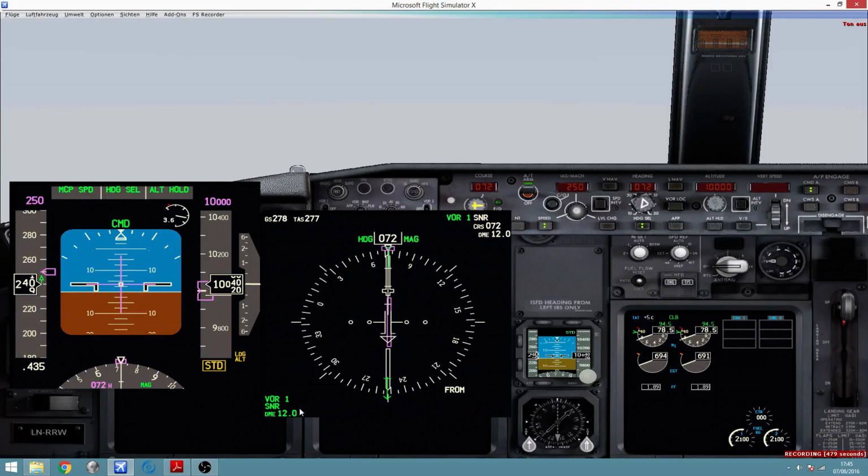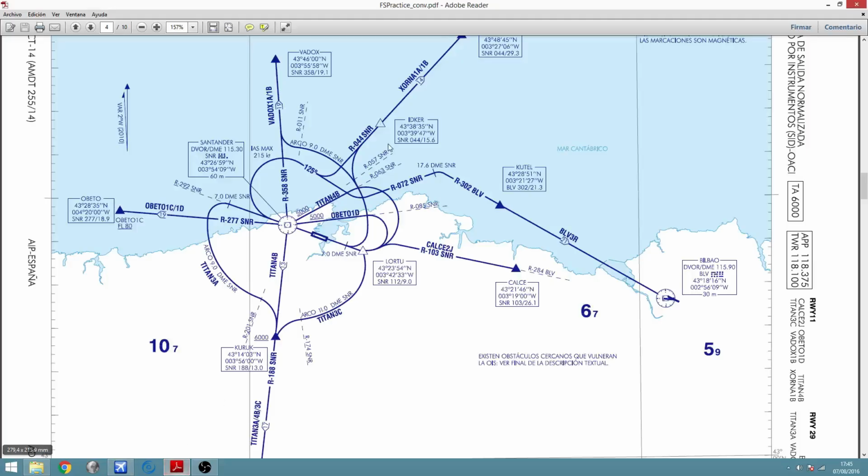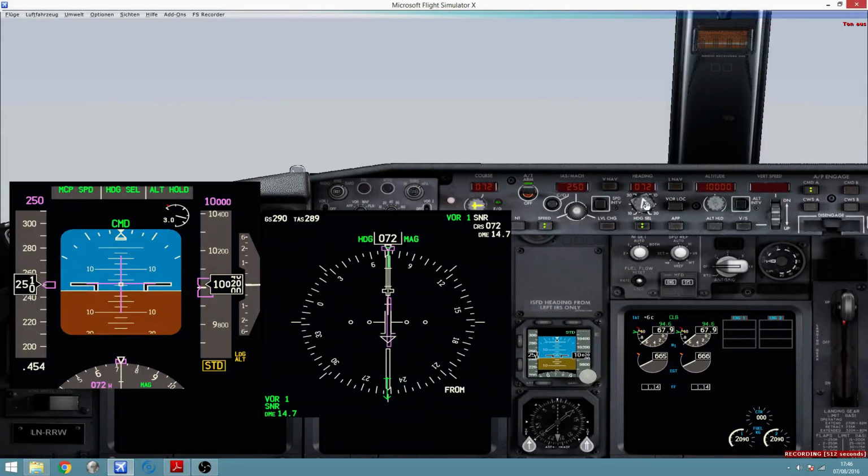Good. I'm only 4 miles from the point that I have selected, that is indicated from this point. And at this point I will continue turning right. On which track? I will look for a track of 302. No, this 302 degrees is outbound from Bilbao. The opposite one should be towards Bilbao. Okay, if this is the north, then this direction is clearly 122, the opposite of 302. So I will have to turn right, looking for 122 degrees. So 15, we're approaching the point.